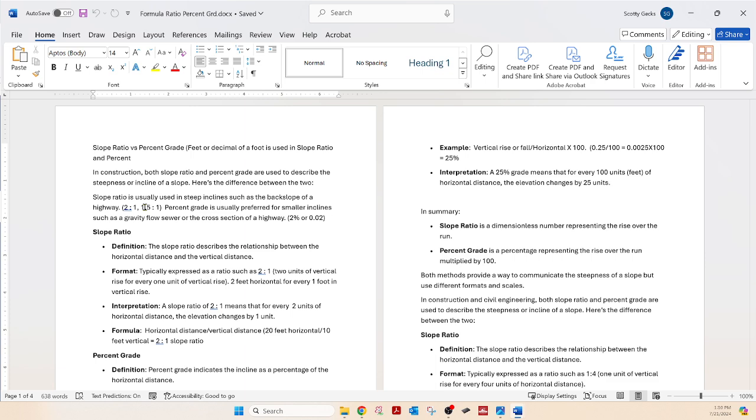Because a 1.5 to 1 slope has a lower horizontal dimension than a 6 to 1 slope. A 6 to 1 slope would be a long horizontal, and the horizontal from the very back of the slope to the edge or center line of the roadway is what's at stake when you're buying right of way. So the steeper the slope, the better financially for the state, if they're doing it.